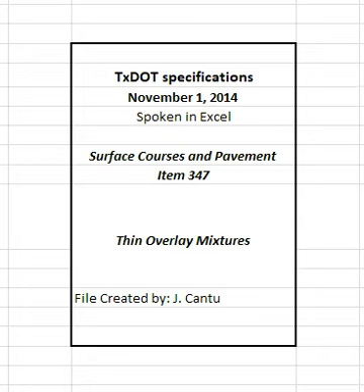4.9.2.5 Individual loads of hot mix. The engineer can reject individual truckloads of hot mix. When a load of hot mix is rejected for reasons other than temperature, contamination, or excessive uncoated particles, the contractor may request that the rejected load be tested. Make this request within 4 HR of rejection. The engineer will sample and test the mixture.